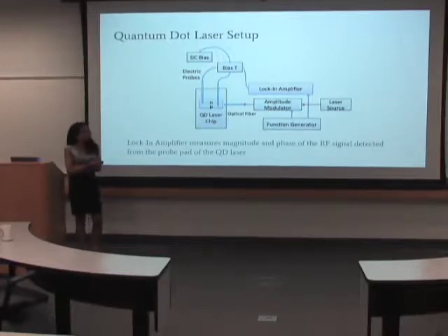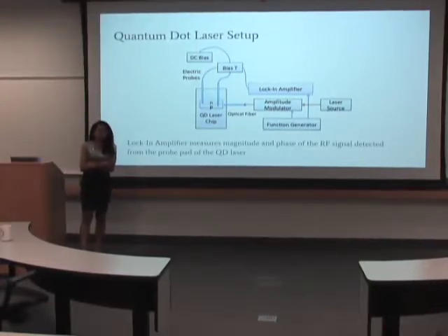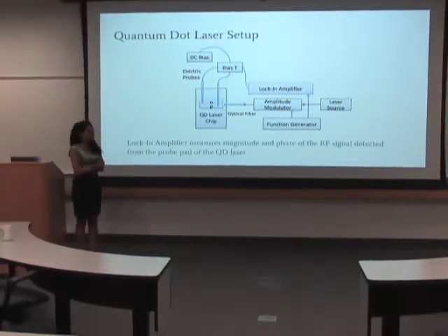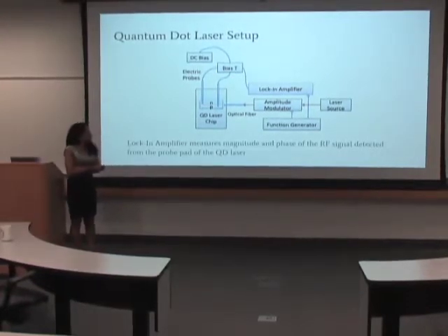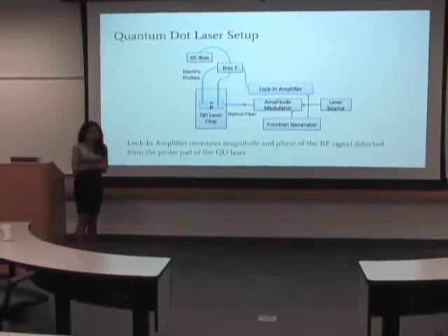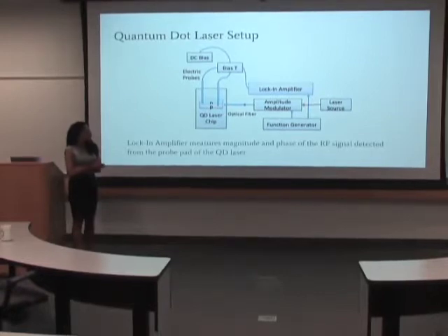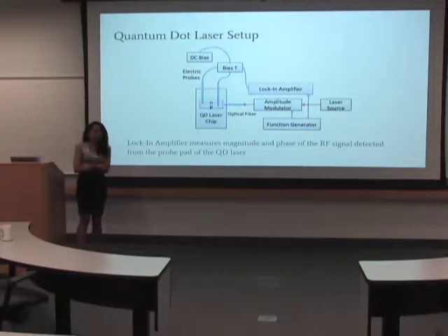So we found this graph after putting the laser at port 1 and the photodetector at port 3. We were able to get this graph, which is after sweeping the wavelength, and found the wavelength versus power graph. By using the max and min points of the graph, we were able to find the ratio that is used in this equation. Then we did the same thing for ports 2 and 4, and were able to find the ratio for 2 and 4.